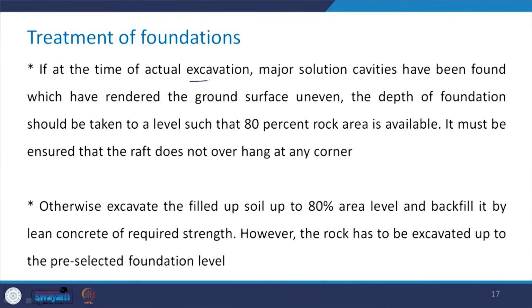If we are not getting adequate bearing capacity of the foundation when we are putting it on a particular type of rock or rock mass, then in such a case one can go for some kind of treatment of the foundation. Let us see what all those treatments can be. So, if at the time of the actual excavation, major solution cavities have been found which have rendered the ground surface uneven,